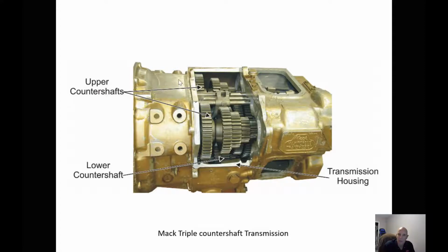If we're not paying attention when we assemble it, and we don't check to make sure that it goes through all the gears, and we stick it in the vehicle, start the vehicle up, put it in gear, and release the clutch, it's going to shear that bolt off, and that bolt could get jammed between some gears and wreck the transmission before it even gets out the door. So always check your transmissions once you've finished rebuilding them to make sure that it goes into all of the gears and doesn't bind.